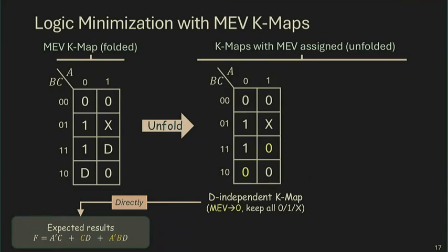All right. So in this example, I need to find some product terms, some implicants that do not depend on the D variable. To do that, I focus on the minterms shown as ones in the K-map. These are the minterms that are definitely minterms, dependent only on ABC. Once you assign some values for ABC, these minterms will produce an output of 1.